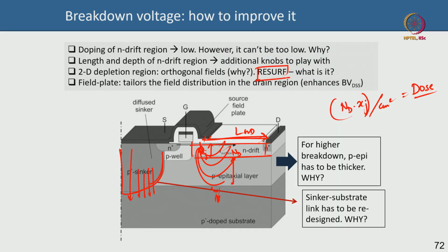I will come to that. RESURF helps improve the breakdown field without compromising the on resistance, and it is unique to silicon devices, very hard to implement on a III-V device, because you need a p type layer below, which is not there in a III-V device. Why is there no p type layer on the III-V device? You should try to answer yourself.